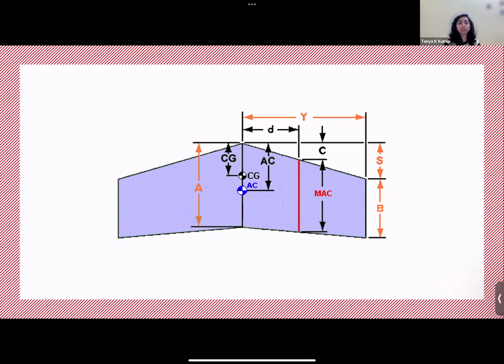And then the next thing was to add weight. Initially I had taken a thermocol sheet. The aerodynamic center is somewhere at the quarter chord point. So this is the aerodynamic center, and the CG is here. Without adding any weight, the initial CG is here. So when I fly this, it would not fly stable. It would not be a smooth motion. It would keep flipping over. And so we require the CG to be ahead of AC, right?